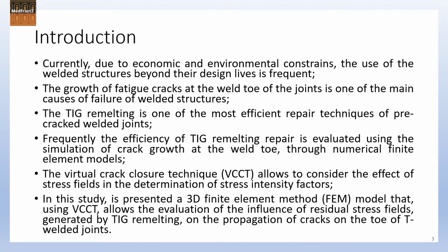numerical finite element models. The virtual crack closure technique allows to consider the effect of stress field in the determination of stress intensity factors. In the study is presented a 3D finite element method model that, using VCCT, allows the fatigue life evaluation of T-welded joints repaired by TIG remelting.